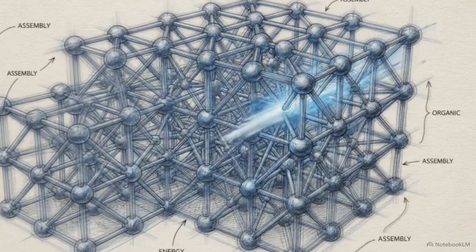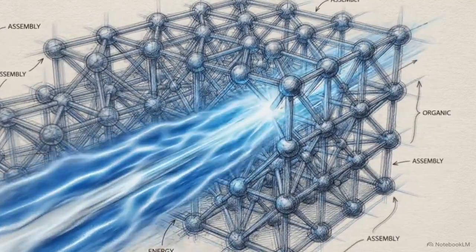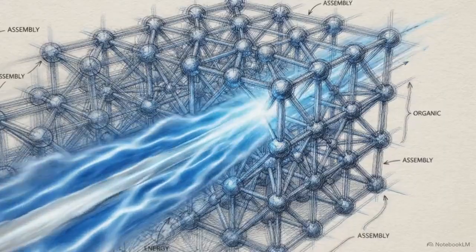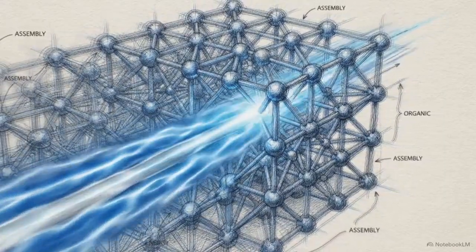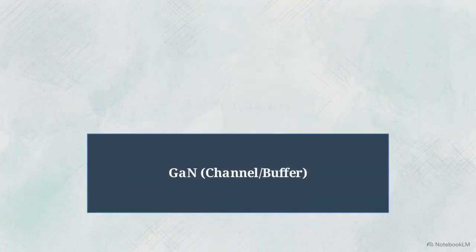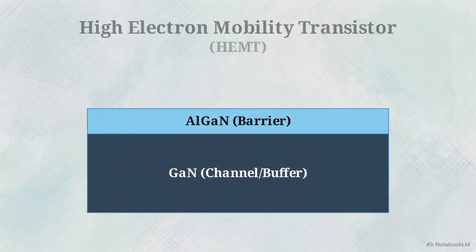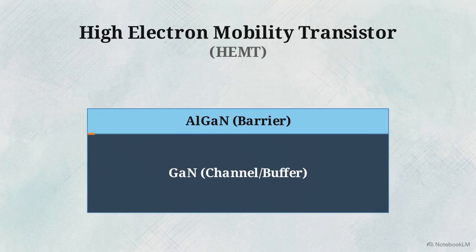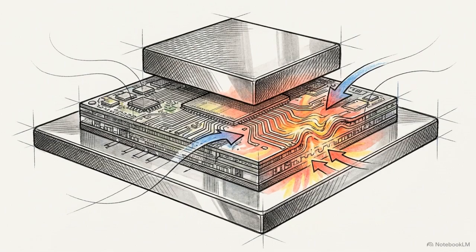Inside a high-frequency power system, raw electrical energy constantly pulses through a dense, microscopic crystalline lattice structure at absolutely extreme velocities. Modern power electronics depend on gallium nitride high-electron mobility transistors, or HEMTs. These devices rely on a two-dimensional electron gas, a highly conductive layer that allows carriers to move with high mobility. However, conventional GaN HEMTs face a recurring physical limitation.